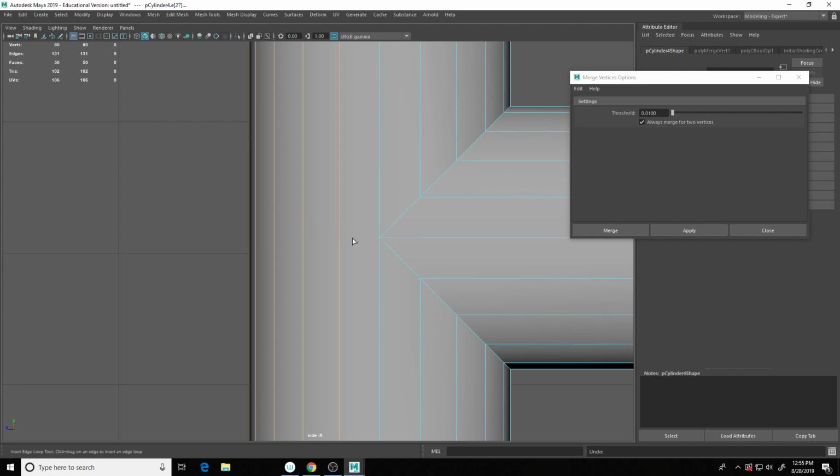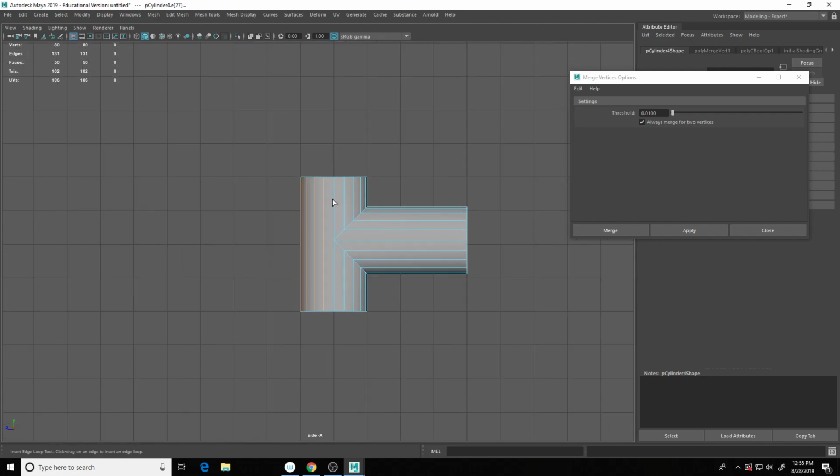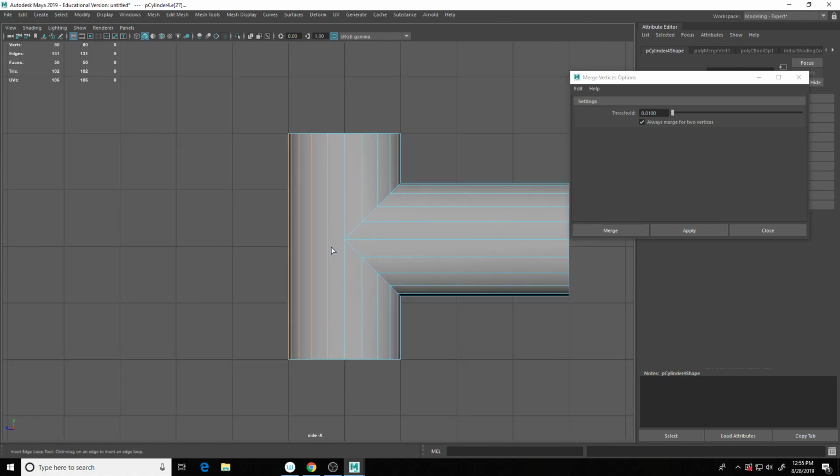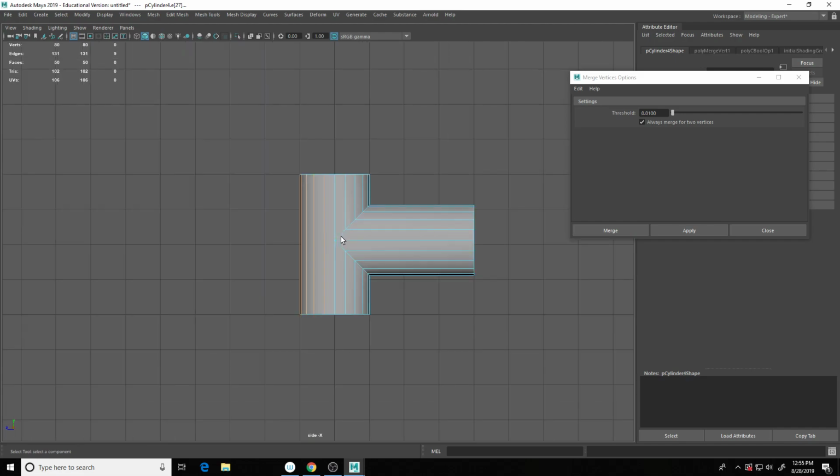I'm trying to put an edge loop in, but because this polygon, or this n-gon, in this case, has 5 sides, it won't work. Polygons have 4 sides. Triangles have 3 sides. For our counting purposes, that is important. Anything that is not 3 or 4-sided is wrong and called an n-gon.